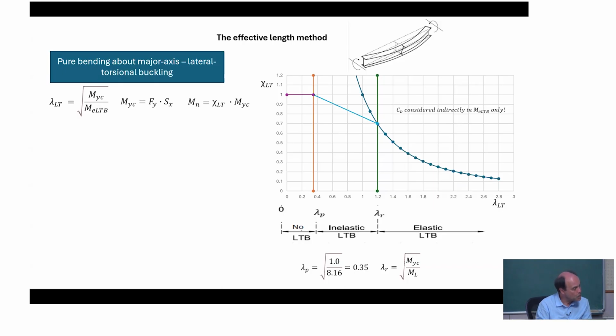Sorry? I don't think the Indian standard shows the F parameter in your code that gives you some additional help from the moment gradient. Right, that's not there in the Indian code. Okay, so then you are fully in line with these. So no other consideration, although something could be, but it's a bit foggy. And in the case of slender webs, probably that could be equal to 1.